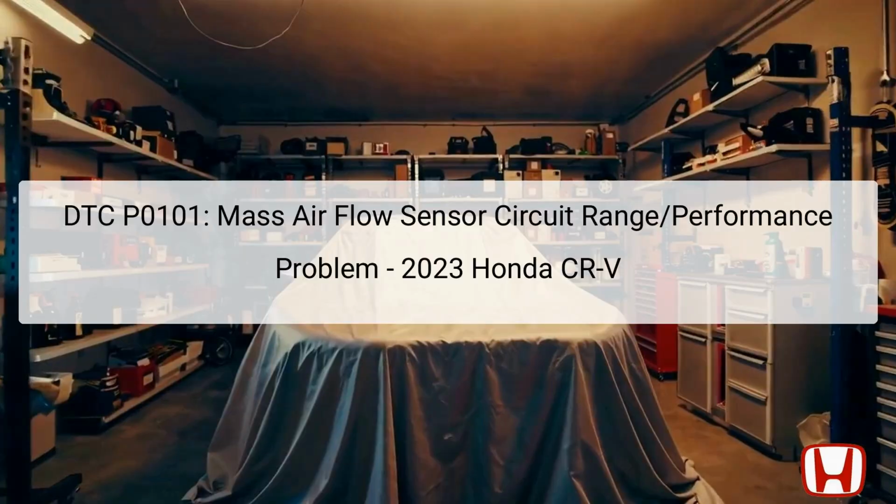The DTC P0101 pertains to a mass airflow (MAF) sensor circuit range performance issue commonly found in the 2023 Honda CR-V. When the powertrain control module (PCM) detects that the output frequency from the MAF sensor is out of the specified range or the signal is abnormal, it triggers this diagnostic trouble code.